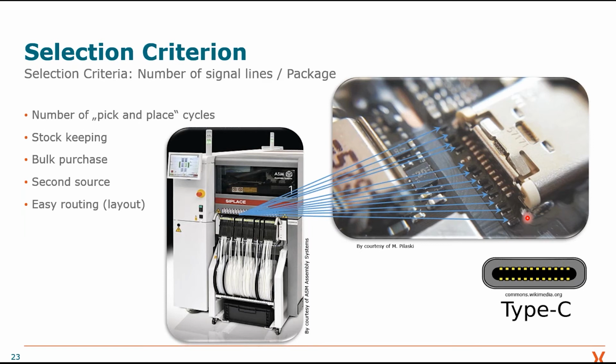We often get questions about capacitance matching. Do I sacrifice something? Do I have disadvantages when using single line protection? Not really, because in terms of capacitance matching, the relative deviation is similar. So if I have a bus with 20 picofarads, and I may have a USB bus with 2 picofarads, the deviation is similar.